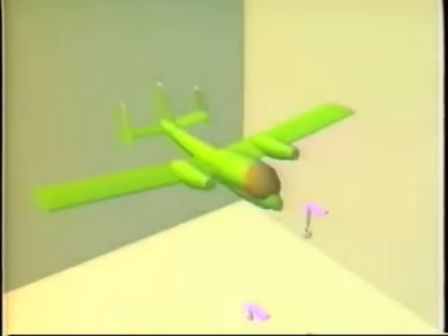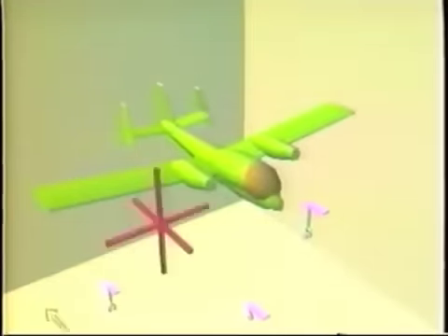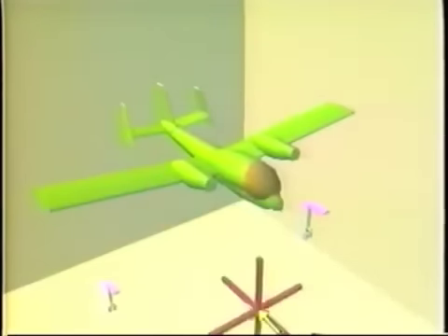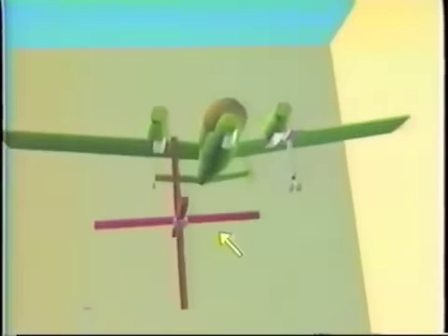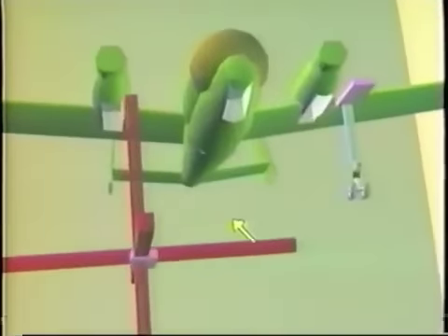This next segment shows a common technique for snapping 2 objects together. We first choose a point on the surface of the landing gear that we want to attach to the plane. Then, by manipulating the camera, we find the point on the surface of the plane that we want to snap to. The difficulty here is that we would have to change the camera again to snap the rest of the gears.